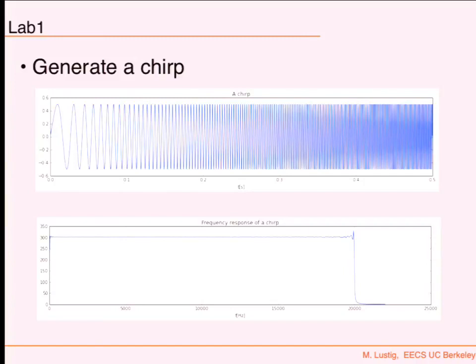So you transmit some signals you want to pick up, and you're in a room. There's going to be some frequency response of the room, the speaker, and the microphone. All of them together will turn into a frequency response. I could have just sent a pulse. The problem is that the speaker is not able to produce a good pulse. But if I send frequencies and change them slowly, then I could look at the frequency response. So this is what you're going to do.